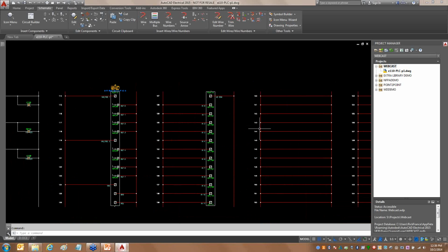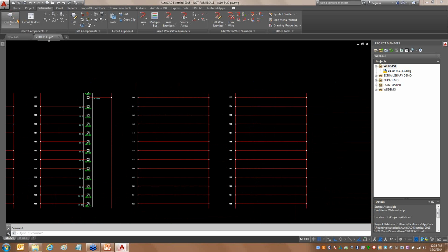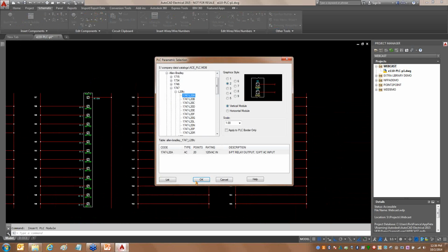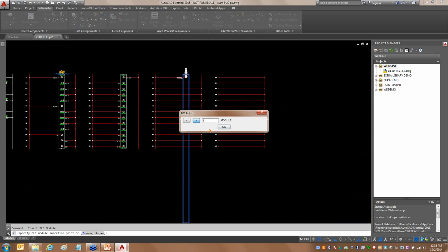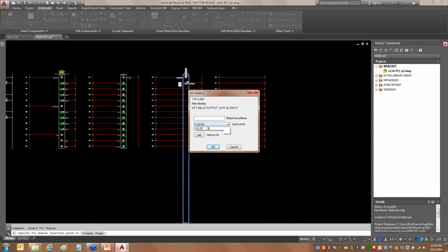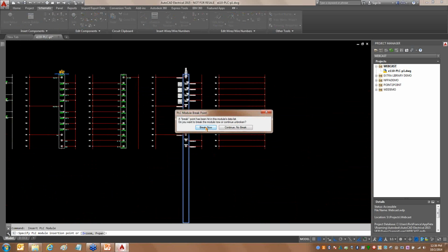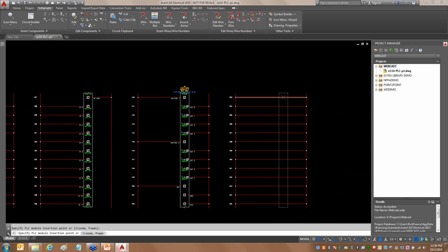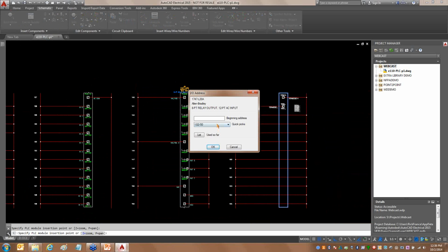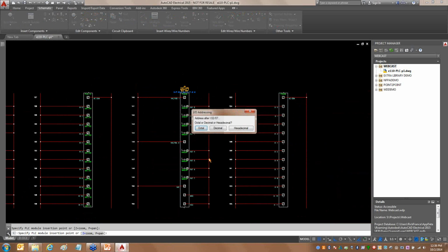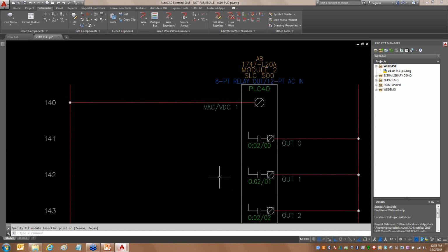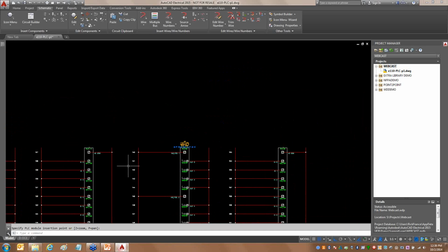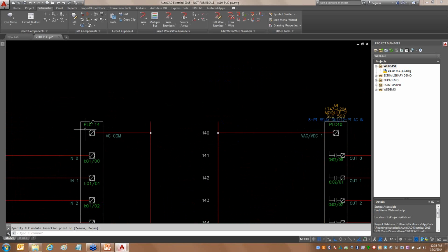If I come back in here and put a second PLC in here, same exact one. Okay, module 2, okay. Break it and place it here. Decimal. Back to PLC 40, because that fix, done through the component, only fixes the current one that I'm working on. It won't fix it in the database.